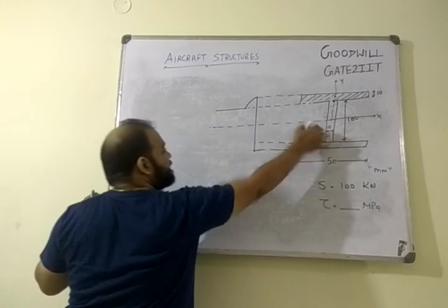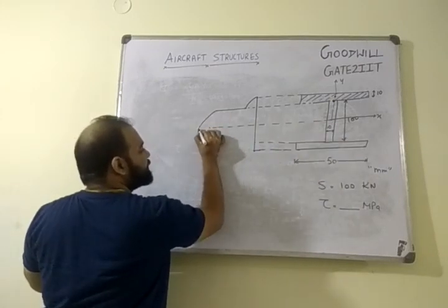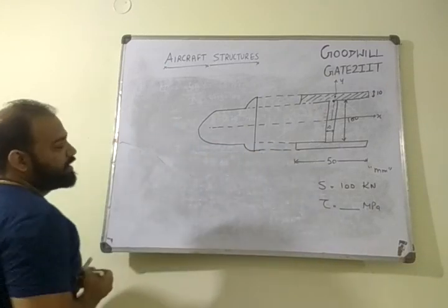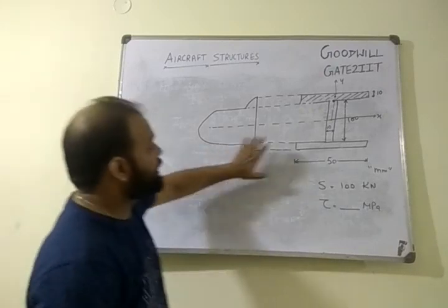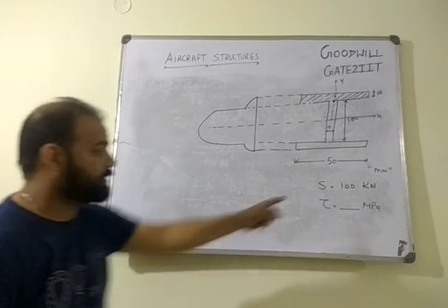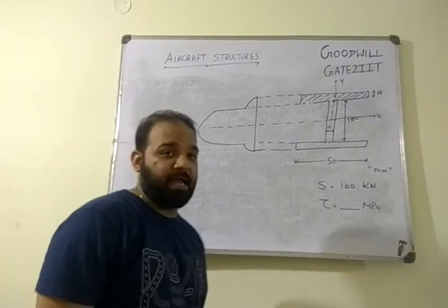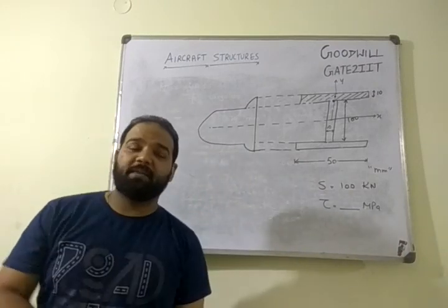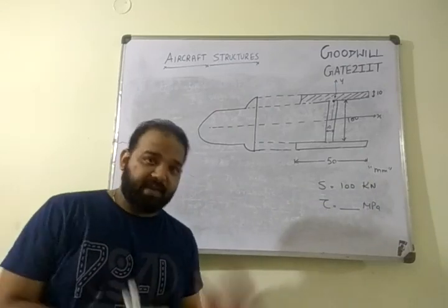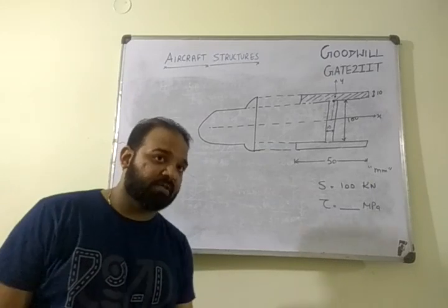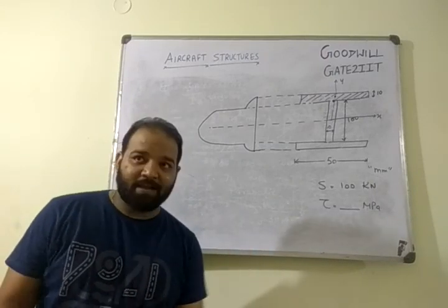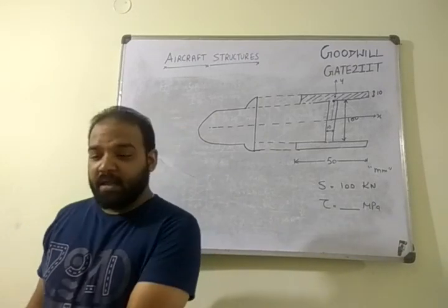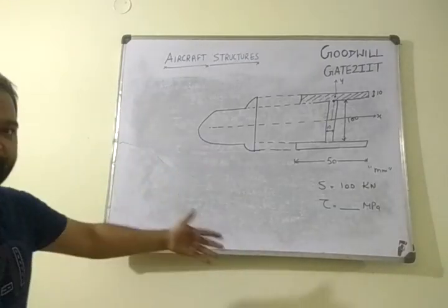And after this, if you move in web, right, we know it is parabolic, maximum here, then it comes out to be like this, then it becomes like this. So this is how your shear stress distribution looks like for an I section beam, which is subjected to a load of 100 kilonewton and magnitude we have calculated. I hope this is clear. If you have any doubt in any of the topics we have discussed today, please let me know. We can have an additional lecture prepared, and definitely we have a separate lecture for solving all the numericals related to shear stresses. So maybe I'll combine that with shear force and bending moment diagrams also. So it's like, first you see a beam, calculate a shear force, and then calculate shear stresses corresponding to it, and complete formulation of a beam.